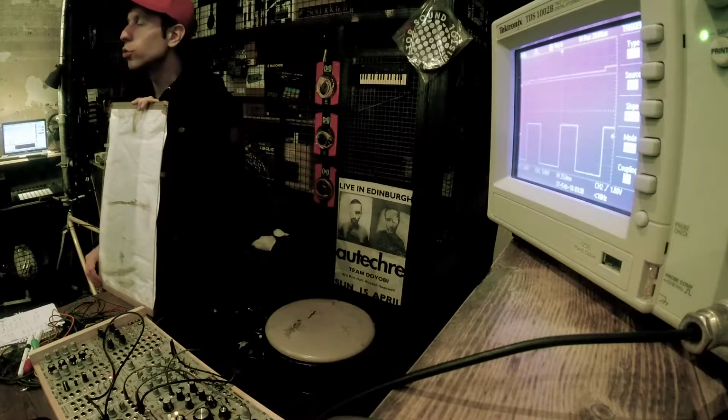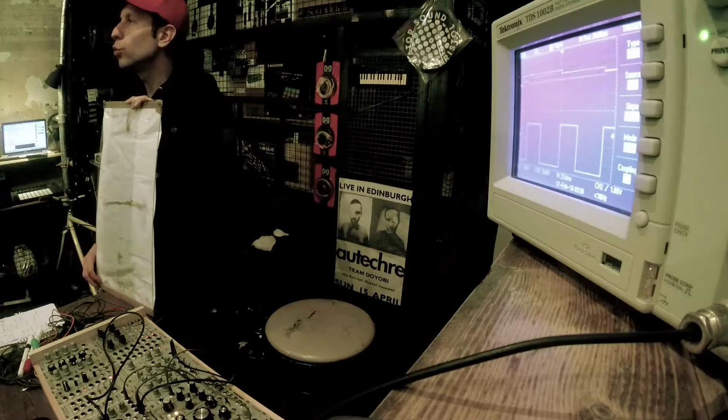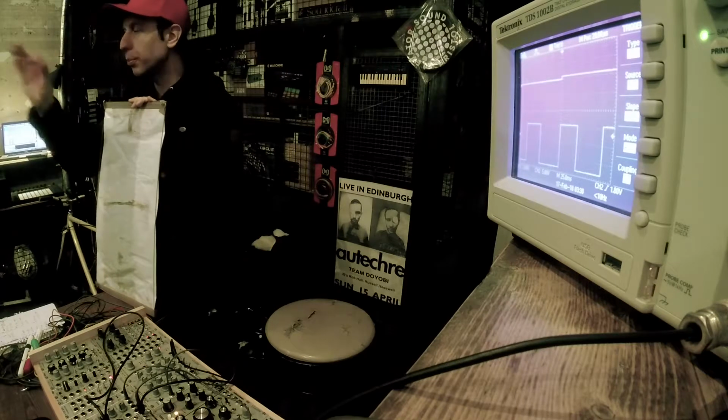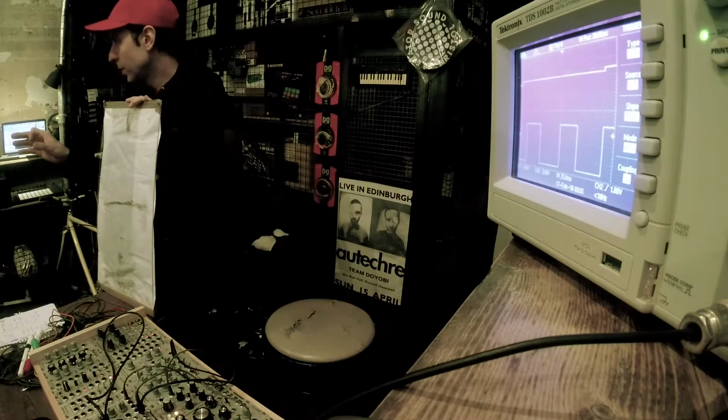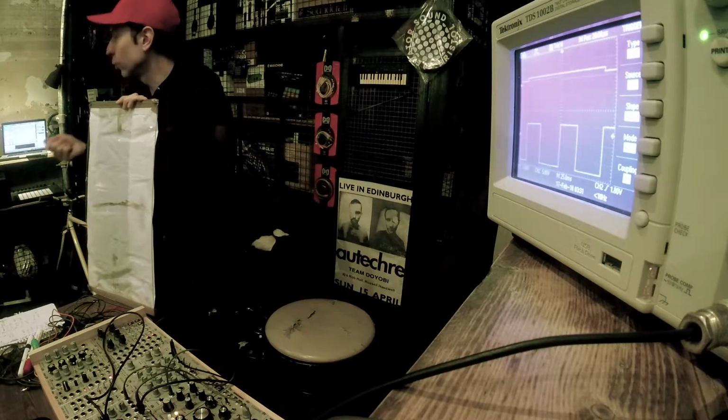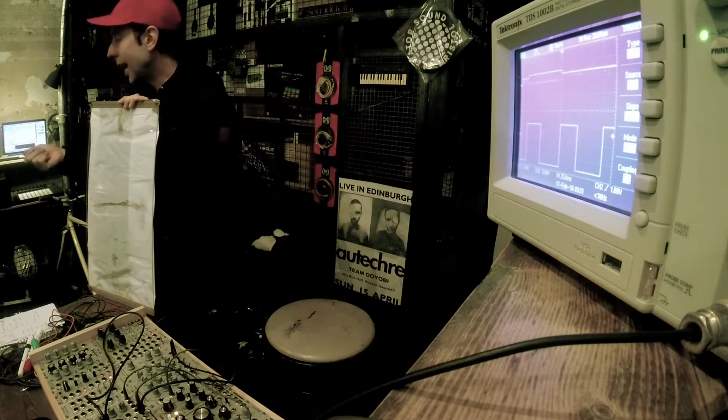None of the modules would allow you to scale and offset the input signals. They had separate scaling and offsetting, so you're always aware: this is the raw signal that my module gives, I want to control the frequency, and there is no CV control on the frequency.